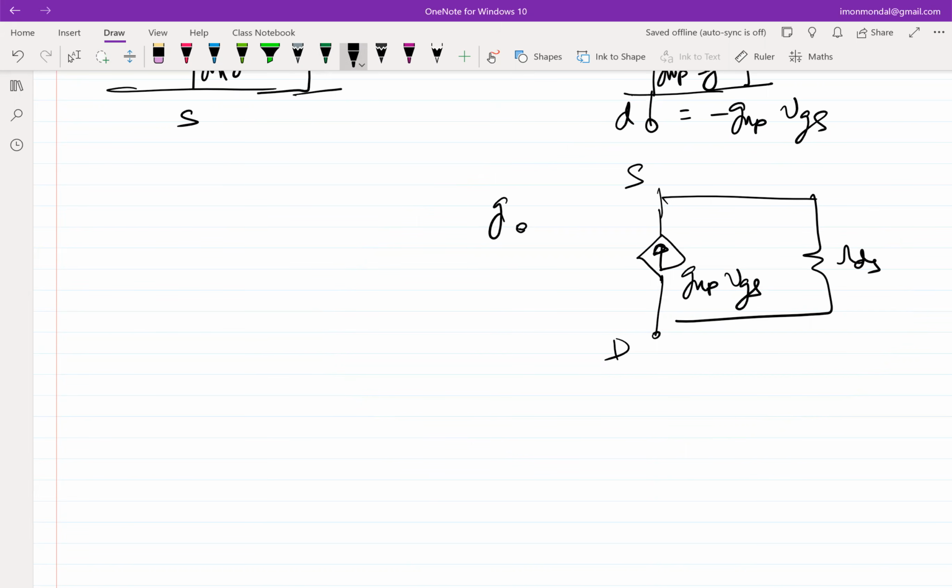Where do you apply the input? You have an input, VI, RS. Where will you apply the input? At the gate. In a single transistor common source amplifier, you apply it at the gate, right? So we will apply it at the gate. Fine. So if I apply at the gate, what do you do at the source? The source should be incrementally grounded, right? In the case of a common source amplifier with NMOS, the source was incrementally grounded. So we grounded the source incrementally.